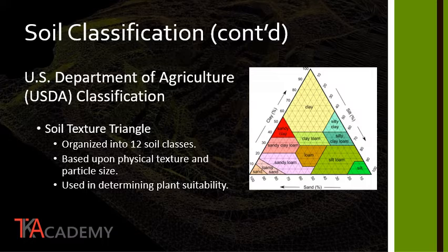There are some similarities between the soil texture triangle and the USCS classification system. For example, the different particle classifications of clay, silt, and sand. This triangle is read by knowing the percentage of clay material, percentage of silt material, and the percentage of sand material that is in your soil sample. From here, then, the clay is read as a horizontal line going across a triangle, the silt being a diagonal coming back toward the corner, and the sand being a diagonal read the other way.